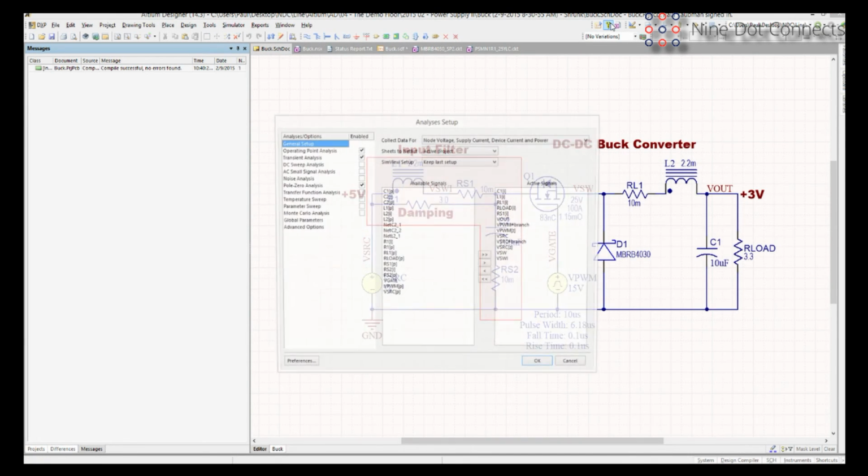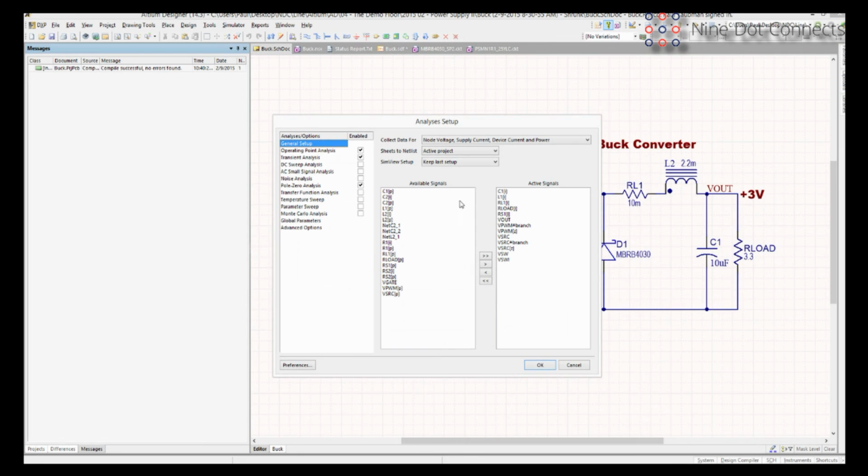We're going to click on the wrench over here. The wrench is really just two aspects: what type of analysis do you want to run? And these analyses are totally based upon the analyses that were built into the SPICE engine. So if you purchase a tool and it's providing something above and beyond what you're seeing over here, it's code that they've added in there to enhance the SPICE engine.